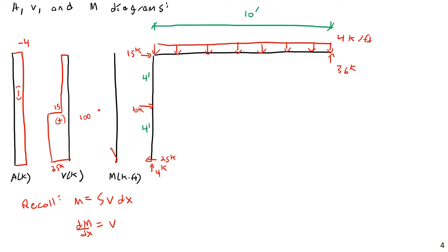Okay, anyway. Can you explain why it's increasing parabolically? Okay, the question is, why is it increasing parabolically? Isn't shear constant? Okay, actually, no, wait, sorry, not parabolically, it's linear. You're right, thank you. I guess it is increasing paradoxically. I'm too used to distributed loads. Yeah, so it is going to be increasing linearly, because the integral of a constant value function is a linear function, so it's going to increase to 100.